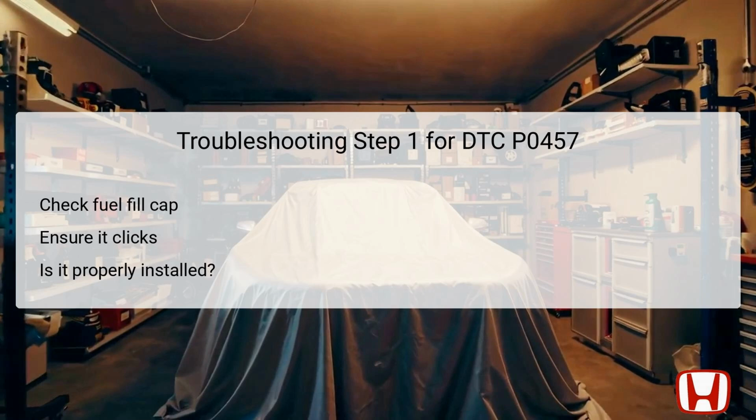Should it be found inadequate, the appropriate action is to replace either the fuel fill cap or, if needed, the entire fuel fill pipe. Once replaced, be sure to carry out a verification to see if this resolves the DTC before moving to further steps.